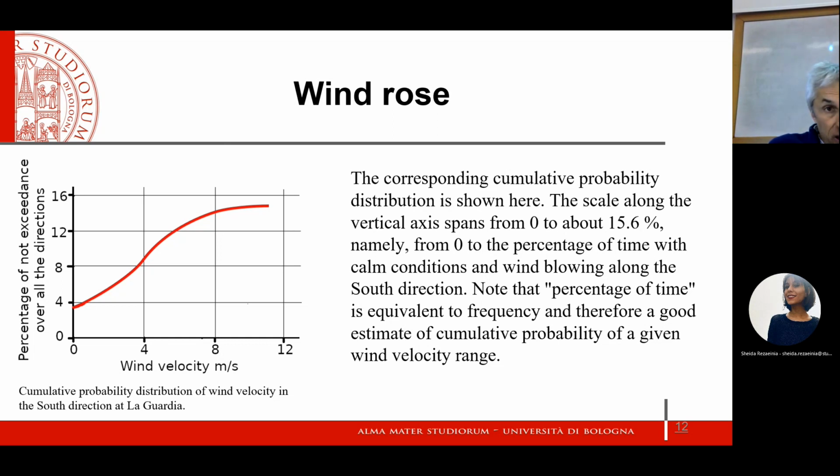It is the highest value that I observed in 100 observations. Given that any observation is made once a year, if I have 100 observations, the observation period is 100 years, and the highest value occurred once in 100 years. So the probability distribution, giving you an estimate of the frequency, allows you to estimate the return period. Of course, I think you know this, but I just want to stress the concept.